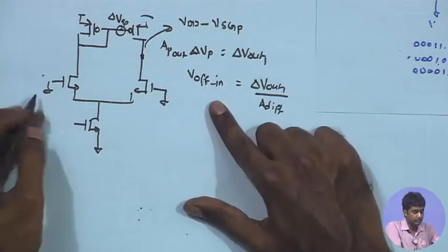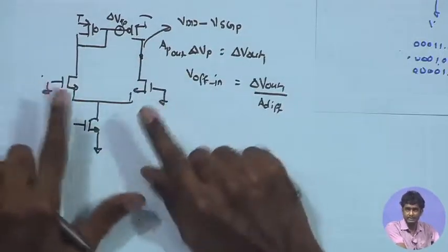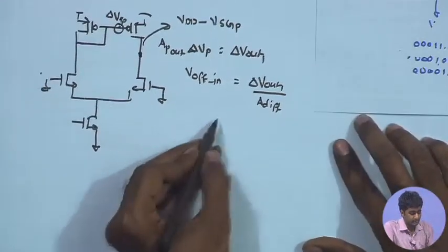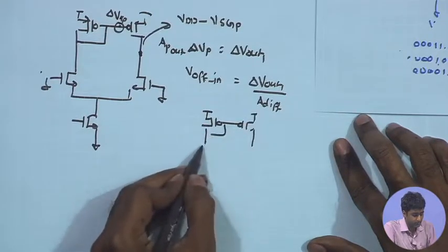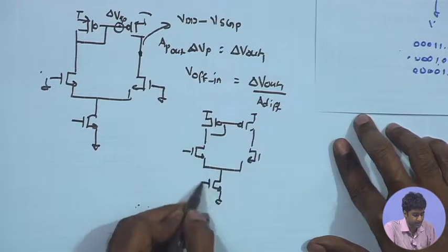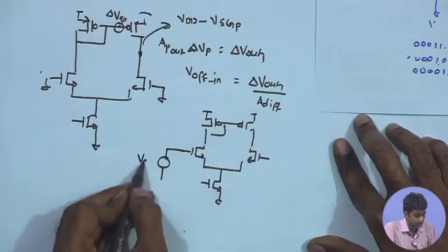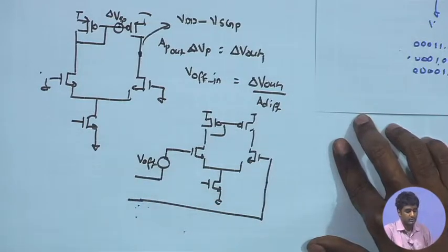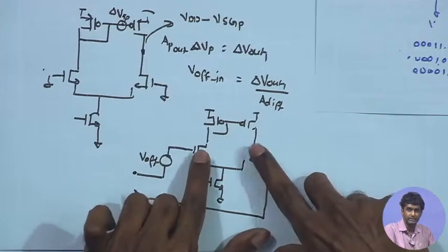And therefore, for the external user, if I have designed and characterized this transistor circuit, this is the input referred offset. I can model this input referred offset as an ideal, perfectly matched differential pair where all the transistors are very well matched. I have taken the contribution of mismatch in these two pairs and added them together, so effectively I have some V offset present in the device. This V offset has the effect of delta Vt, or the mismatch in these two devices.